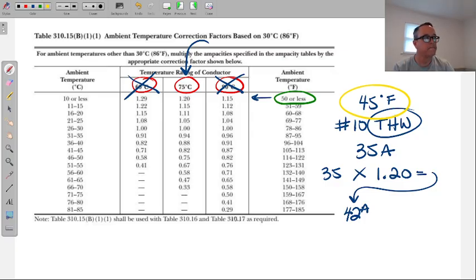Okay. So it's like wherever you're located. I just use that number as a reference point. It's based off a few factors. Again, the length of this conduit run is going to play a role in the heat temperature factor. Is the conduit in free air? Is it not free air, but the conduit itself? Is it outside? Is it buried under the ground? All of these will take us to a temperature.